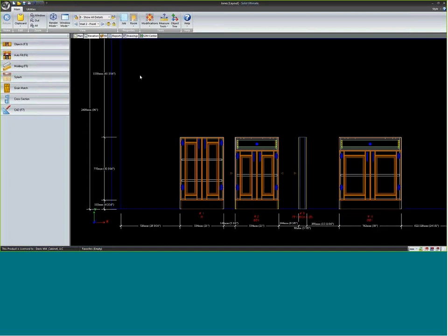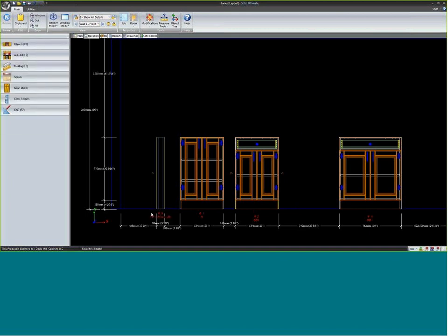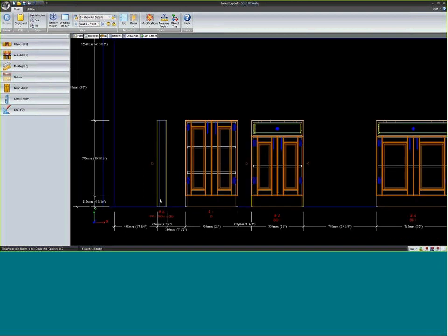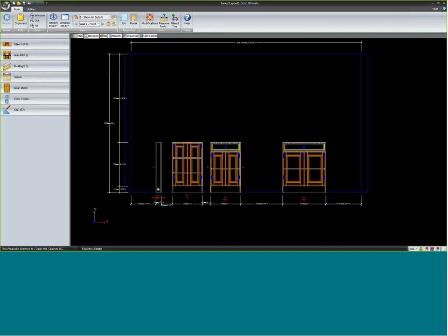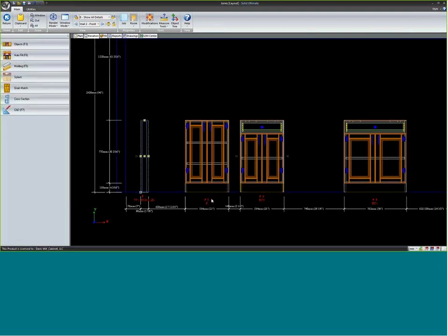This lock feature is so that I've locked down my numbers. Now I can move this up and it will retain part number 3. So that lock feature is for if I unlock, notice they stay the same. See what happens if I move this one. There, moving it, it refreshed everything and renumbered. Okay, so that's what the lock feature is for.